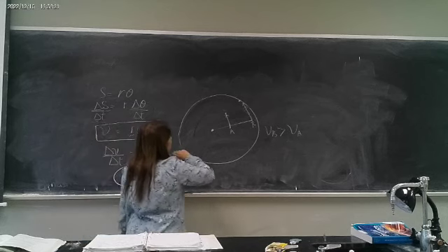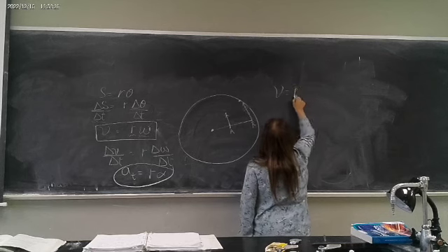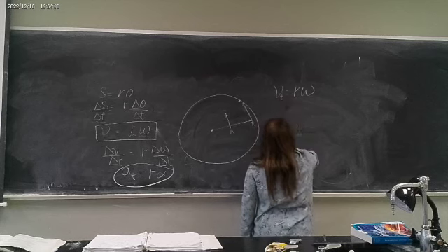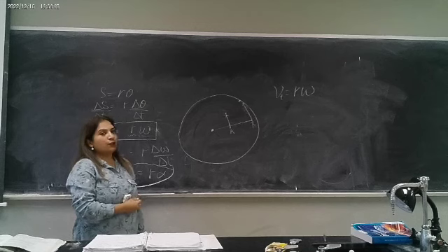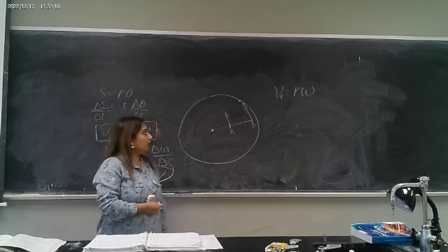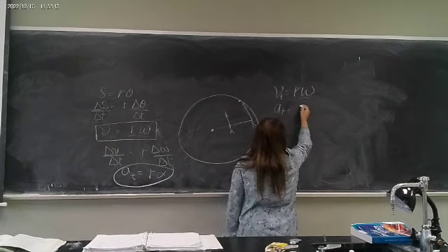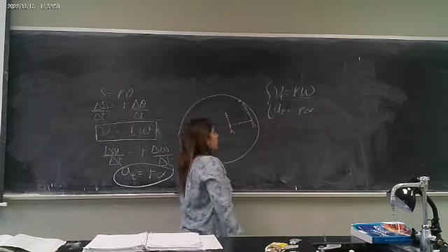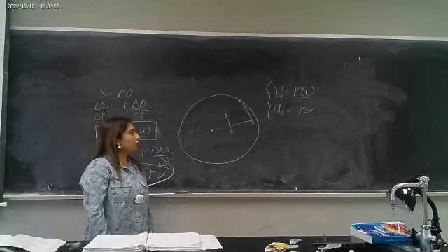So there are two equations which define the relationship between the linear and the rotational quantities. We can put a little t there because it is this velocity which is directed along the tangent. This is the same as the linear speed, and this is the angular velocity, and we can also define a_t equals r alpha. These two equations connect the linear quantities to the rotational quantities.